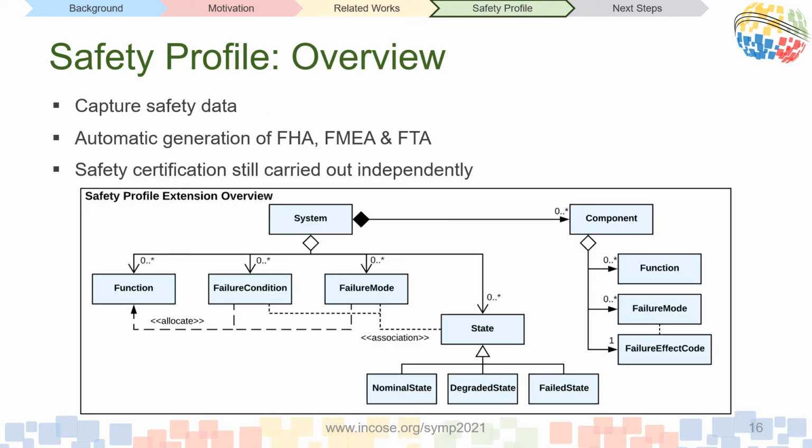So once again, the goal of these newly introduced profile elements is to allow for the capture of safety data within the system model and to support automatic generation of aircraft level and system level FHA, FMEA, and FTAs. However, since safety certification must still be carried out independently as per aerospace standards, the generated safety analysis artifacts would only act as a preliminary document and would still need to be verified by safety experts.